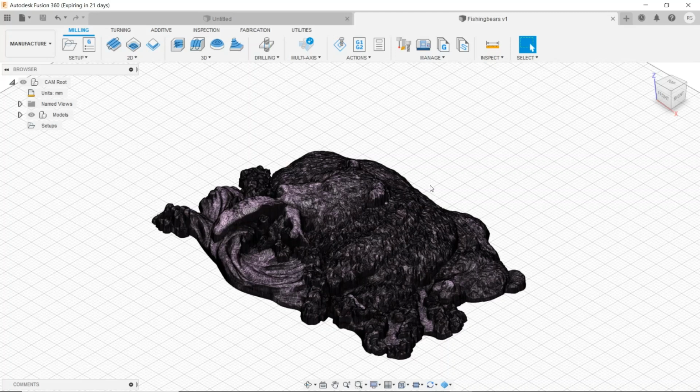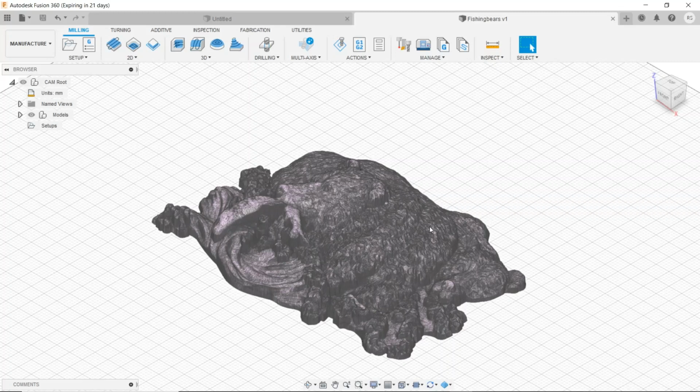I'm going to use a 1/4 inch bit. I suggest you purchase a 1/4 inch flat end mill with 2 flutes. You want the 1/4 inch shank. That way you can mill this the same way I'm doing. It's a lot quicker. You'll remove a lot more material, and it's going to save a lot of wear and tear on your machine.